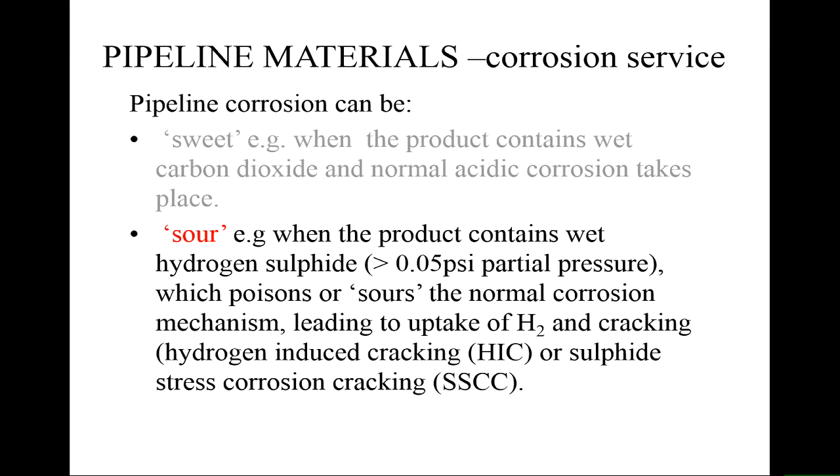What the hydrogen sulfide does is it poisons or sours the normal corrosion mechanism, and that leads to hydrogen being included in the material, leading to hydrogen embrittlement, hydrogen-induced cracking, or sometimes sulfide stress corrosion cracking.